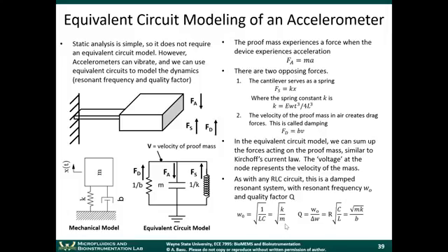If we have a vibrating object and we make that vibrating object smaller, what's going to happen to the resonant frequency? It's going to go up, quite significantly. Look, we have the mass on the bottom, right? Mass is proportional to length cubed. We have the square root of that, but still it's in the denominator. So resonant frequencies go way up at the microscale. This is one of the scaling advantages.